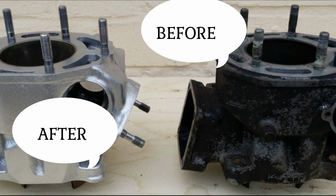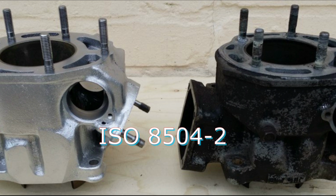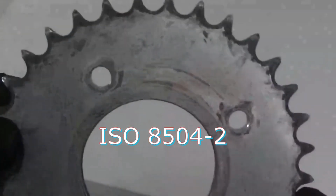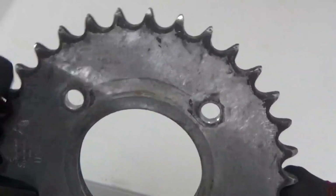The wet abrasive blasting standards help to determine the cleanness, flash rust and surface profile of blasted steel surfaces. They need to be separately specified when preparing a blast cleaned surface. The main standard for steel surface preparation is ISO 8504-2. This international standard describes different abrasive blast cleaning methods for the preparation of steel surfaces.